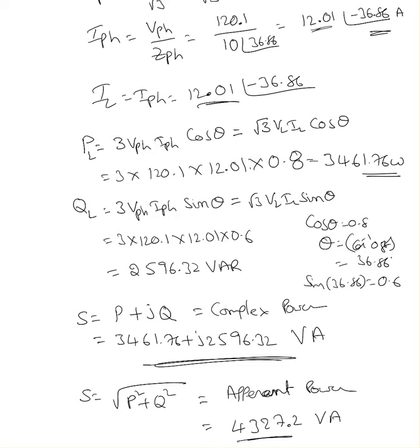By the way, P, Q or S will not have any angles. If you are indicating an angle, that's wrong. Active power is a real number, reactive power is an imaginary number, and complex power is a complex number.